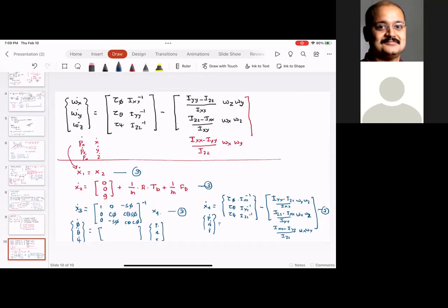So when we simulate these equations in the next class, you would realize that unless you have proper control, some sort of PID control or sliding mode control or some other nonlinear control, the quadcopter will not be stable. These are the quadcopter equations of motion in 3 dimensions. Then we can look at proportional control, proportional plus derivative, and proportional plus derivative plus integral control to stabilize this quadcopter motion.